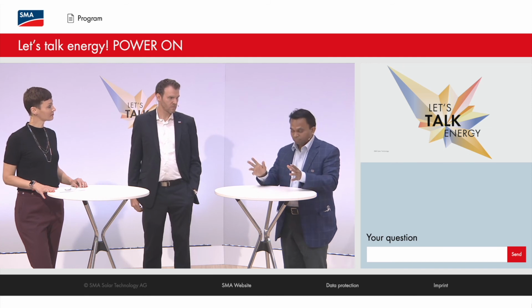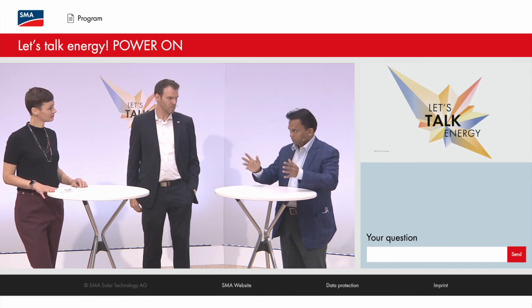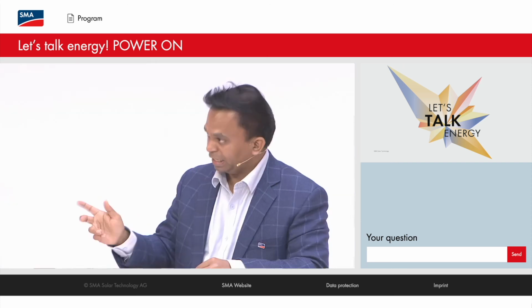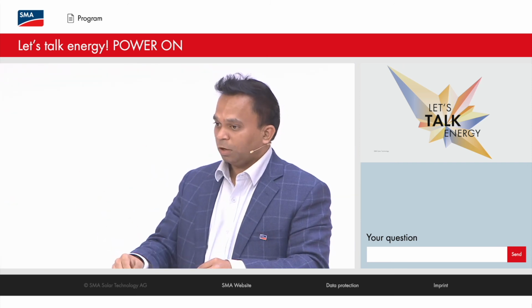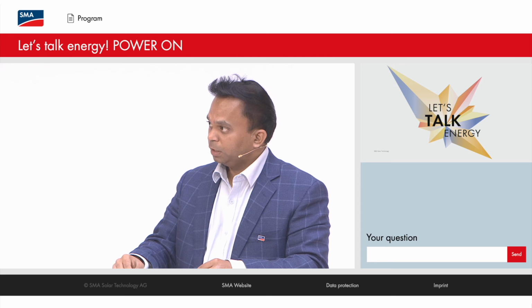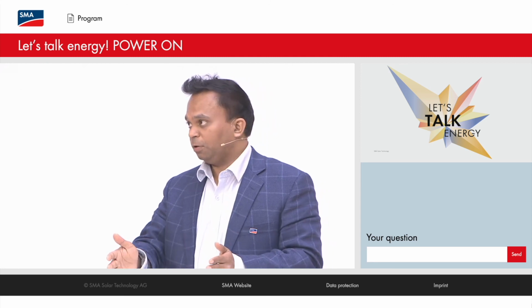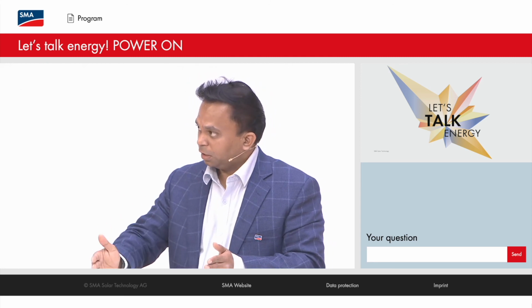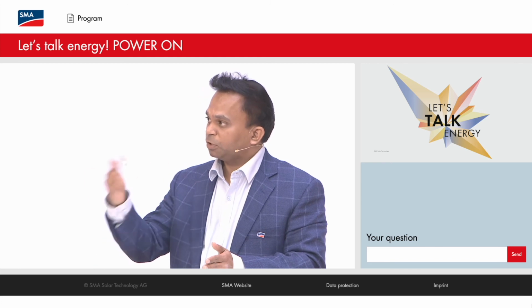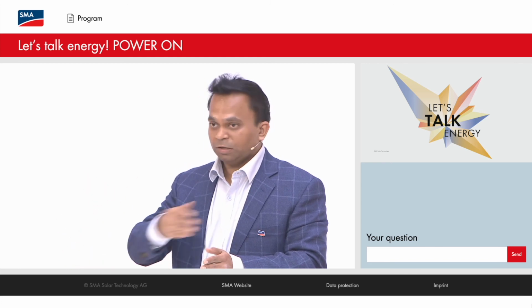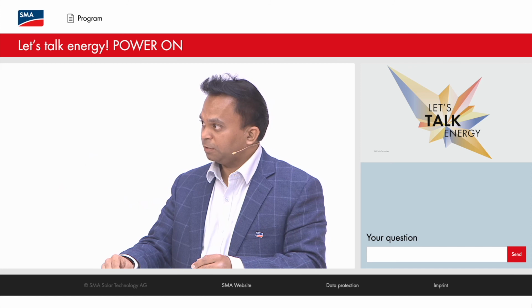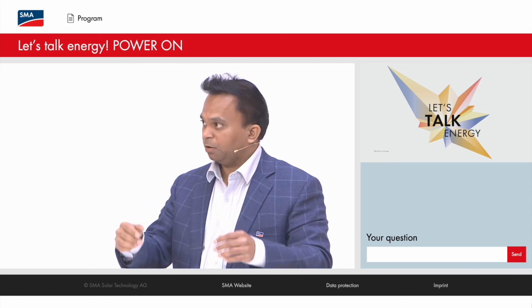We didn't design one, but we needed 2,900 extra components. So in a study, we found that every 1,000 more components increase the risk by 1%. So by that token, in 20 years' time, you would have to replace 50% of the inverters. So that is a big disadvantage that people are not looking at.